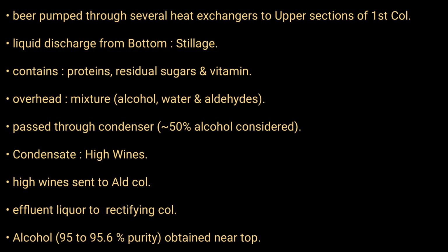The overhead is a mixture of alcohol, water, and aldehydes. It is passed through a condenser where around 50% of the alcohol is condensed. This condensate is known as high wines.